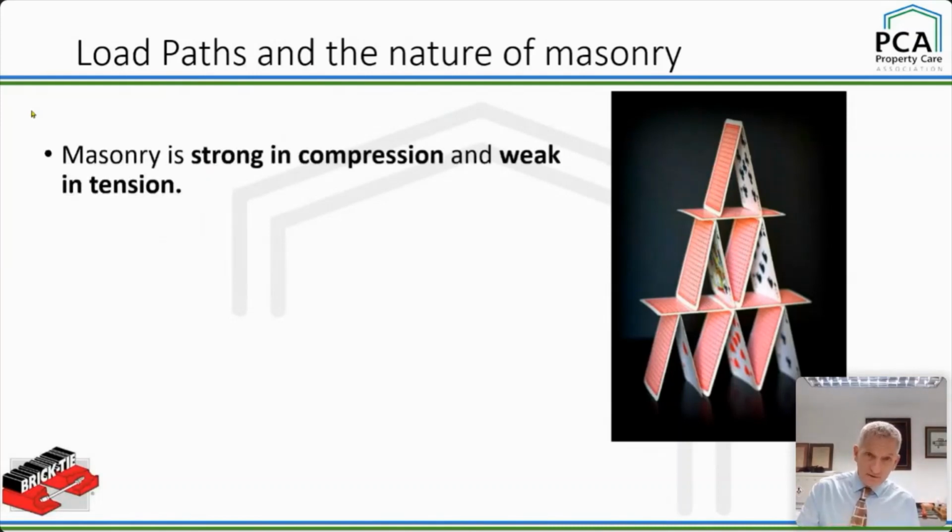Thing to remember, very basically, masonry is strong in compression. Okay, it's very strong in compression. So you student guys, a 100-foot high chimney, Fred Dibnah type chimney, the bricks at the bottom are not getting squashed. They're not getting squashed because they're so strong in compression. But they're very weak in tension. Masonry is very weak in tension. If you try to drag a building one side to the other, or if one part wants to just move slightly away from another part, it's going to rip, it's going to tear.